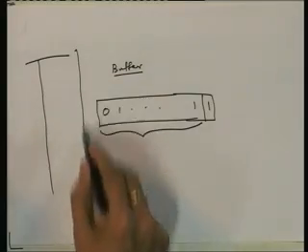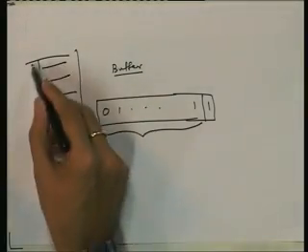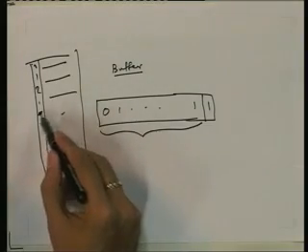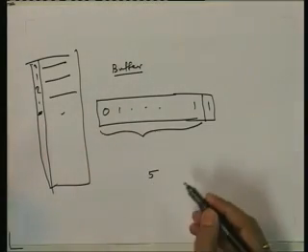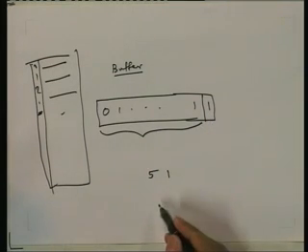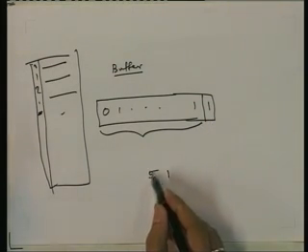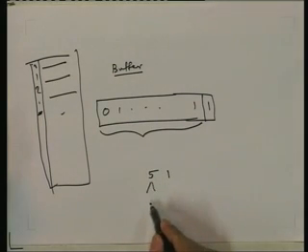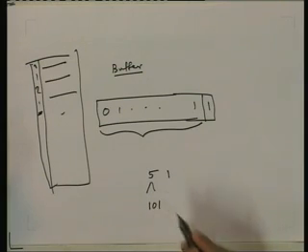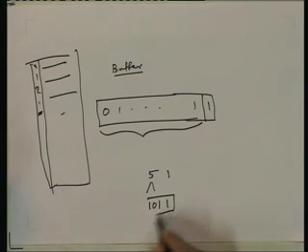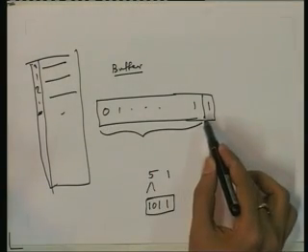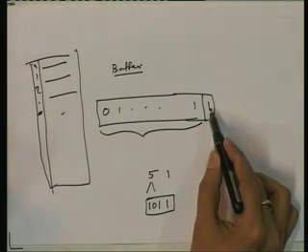There is a list where all these code words are listed, with serial numbers 0, 1, 2 and so on. So, we see the index of that. Suppose it is 5; the 5 is part of the encoded code word. Of course, 5 will not be transmitted this way; we will have its binary, 1, 0, 1, and then the last bit. We will transmit this as the code word. So, we take the index of the substring in the list and then append the last bit to that.